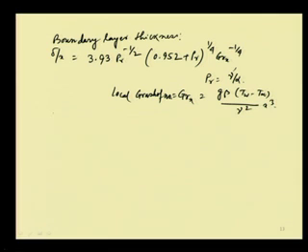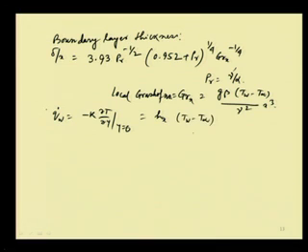Now, we can find the Nusselt number from the relationship that the wall heat flux qw is equal to minus k into del T by del y at y equals 0, and that should be equal to the local heat transfer coefficient hx into (Tw minus T infinity), by convection.